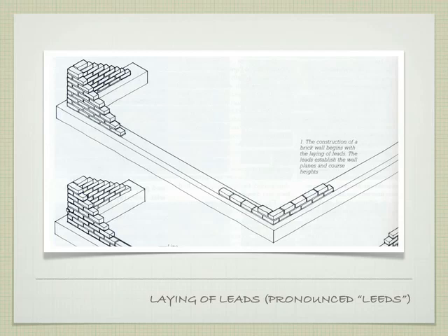A brick building's actually a pretty good solution, right? We have a lot of really heavy things, even in the Midwest where we're subject to tornadoes, right? We have a lot of heavy pieces that are making up our building, right? And when winds and stuff act on the buildings, we have all that weight that's going to keep it in its place, right? So it ends up being a good solution for there. So depending on where you are in the country, right, this is more or less valuable, right?